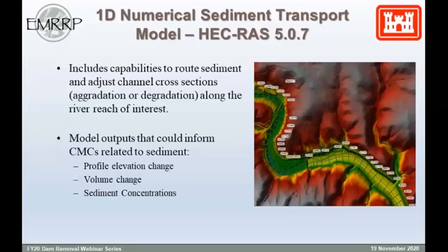But when you do have a sediment model, that initial profile is going to adjust over time based on hydraulic inputs and sediment dynamics. The model can also provide some volume calculations, so you can look at specific parts of your system and see how volume has changed. Have you gained volume? If there has been some erosion, how much volume was lost, things like that. And this model can also predict sediment concentration.